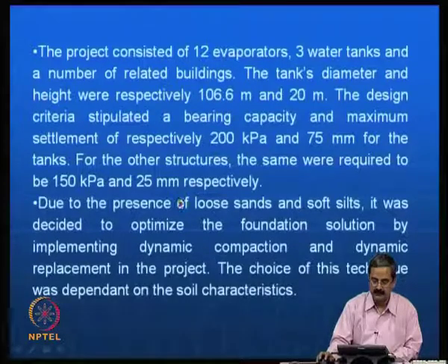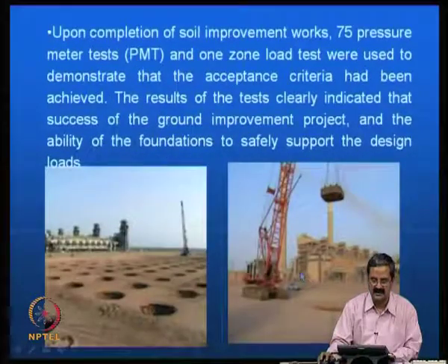Because of the presence of loose sands and soft silts, it was decided to optimize the foundation solution by implementing dynamic compaction and dynamic replacement in the project. So the choice of this technique was dependent on the soil characteristics.